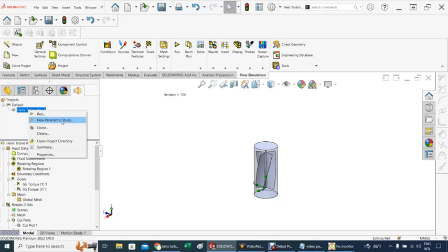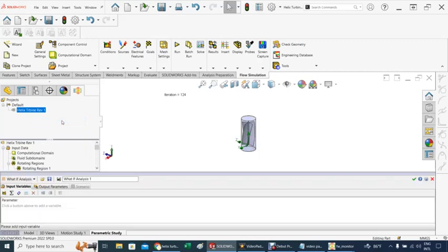If you run a new parametric study, for example, it will pop up a window. And now, what type of parametric study do you want to run? For example, a what-if scenario or a goal optimization. The what-if scenario will run as I was doing by hand, changing the RPM and then allowing SolidWorks to work on that. Or you can do a goal optimization.